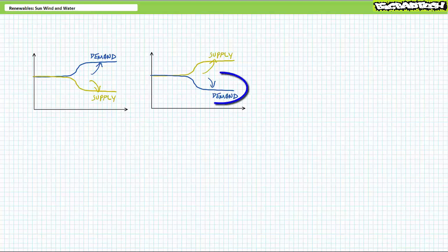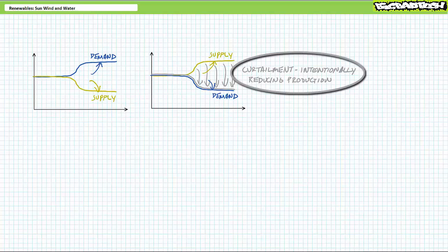Consider the opposite scenario, a ramp down in demand accompanied by a sudden simultaneous weather-induced ramp up in supply, where all the solar and wind farms are at peak capacity. Too much power and nowhere to send it. Without any load to direct this power, this output needs to be curtailed, which is essentially turning off excess generation to meet low demand. Lacking storage, curtailment represents a lost opportunity because all that free renewable power is essentially going to waste. These scenarios illustrate the fundamental requirements towards developing an all-renewable grid.